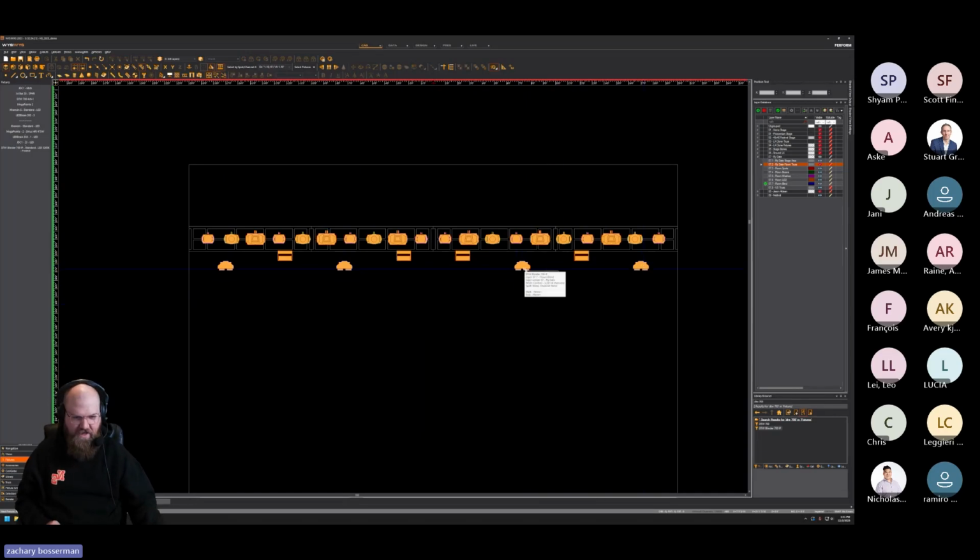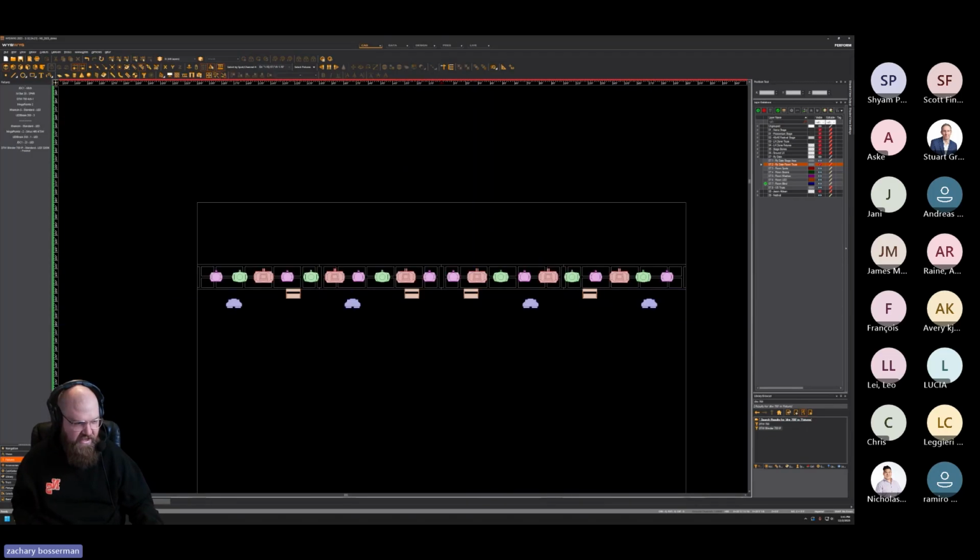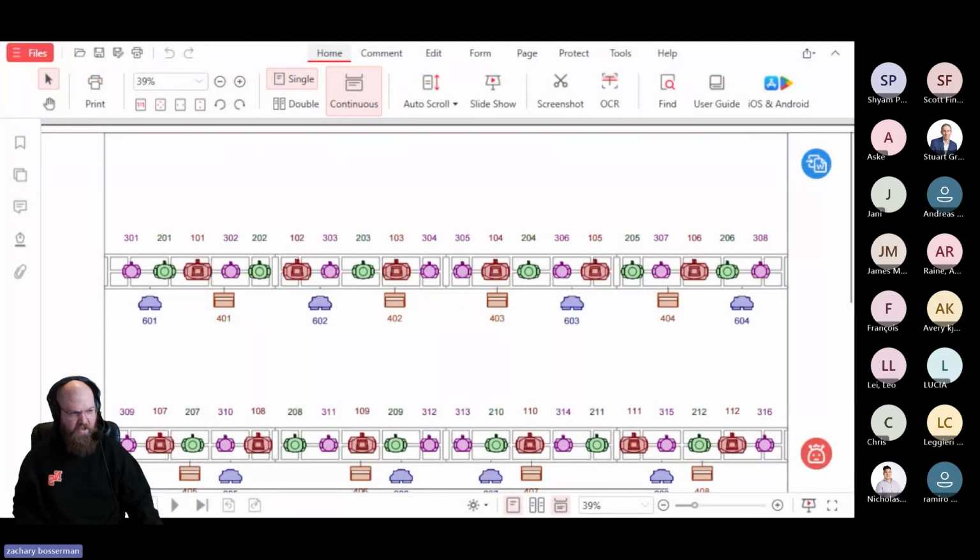You can be looking as you go. You can look either by hovering over to see that you've already patched something, or you can look. It's very hard to tell on this window because I've got a big screen, but on my cursor it says next fixture patch 3.289. So you're able to see as you go what the next fixture is going to be. I'm going to hit F to finish doing the quick fixture tool. And so now we can look, and this truss is built exactly the way it shows in the plot.